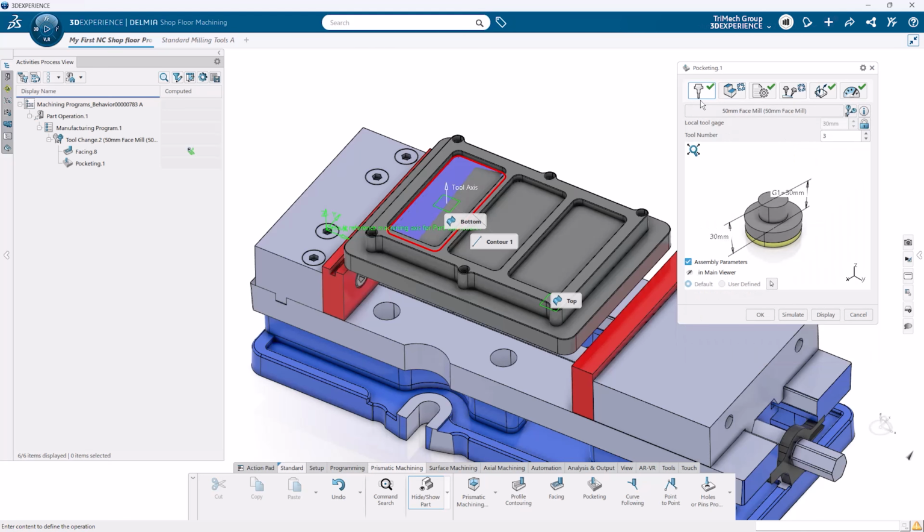To swap our tools, we'll click on the tool name and select a more suitable tool from a search or the sequencing tab, such as a 6mm end mill with a holder. This tool number actually already exists, and we're alerted to this with a warning, but it's easy enough to change it as needed. We'll modify the feature and the strategy for this operation.